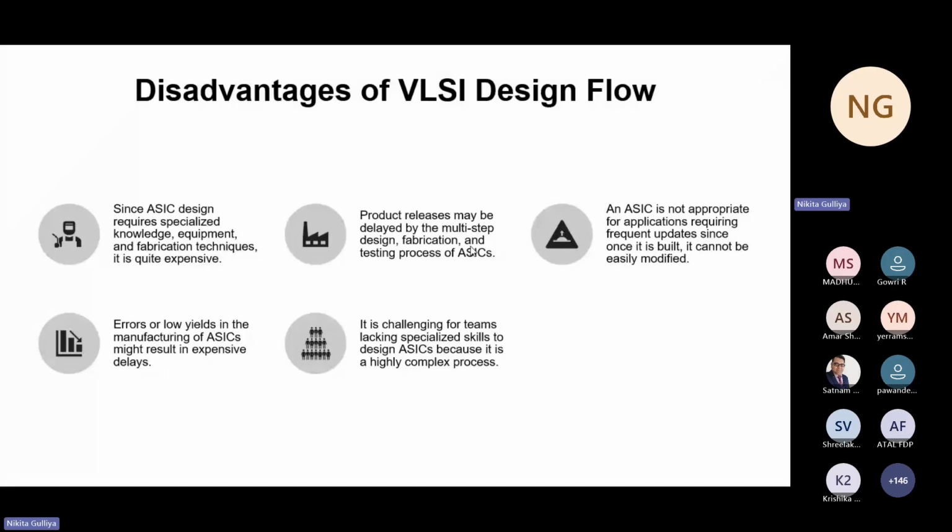Once an ASIC is fabricated, it is not easily modifiable, so it is not suitable for applications requiring frequent updates. Manufacturing issues such as low yield or defects can lead to costly delays. And finally, the high complexity of the design flow makes it challenging for teams without sufficient expertise.